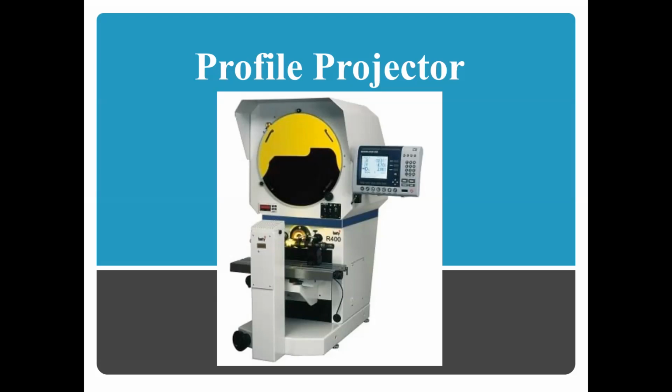Suppose you want to measure the major diameter, minor diameter, pitch of the screw, and thread angle; in all the cases, we project the smaller screw onto the screen by enlarging it, up to maximum 300 times, maximum 1,000 times. In that case, you can clearly see the different features of the screw.